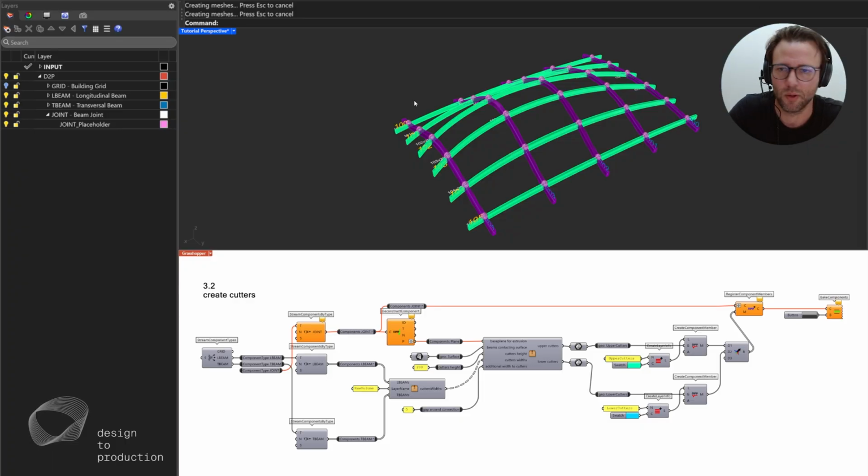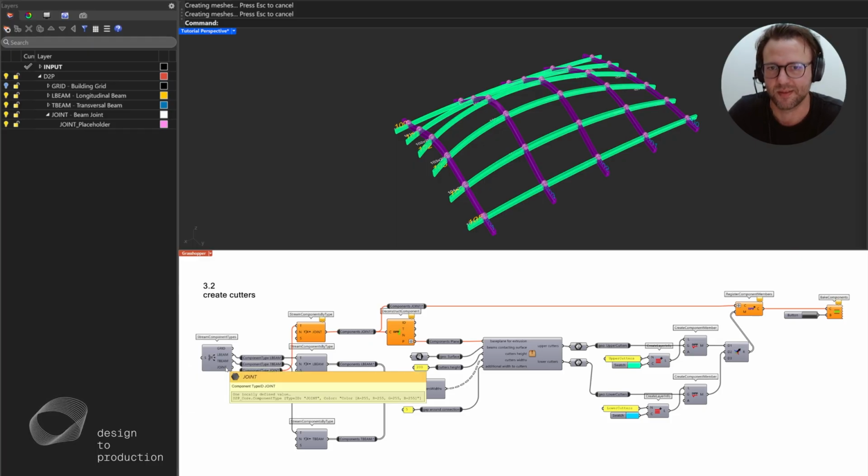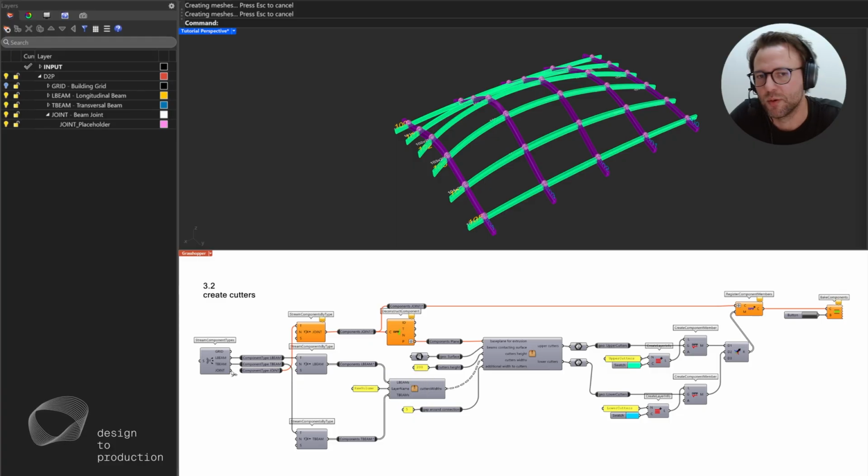So we are going to fill them with live information. First thing we need to do, this is more like a technical issue happening right now. If you set up this component, you need to recompute when using the same file in order to get the latest baked components. So when you find yourself in that file, just bake them, make sure to recompute, and then everything's fine.